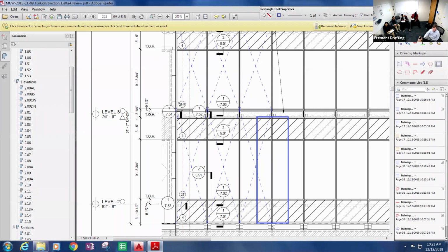So as I look right here, I've got 9.5 inches down here, so 3'10" minus 9.5 is 3'1", so 3'1" from the top of the floor. So let's say the anchor was 3 inches down from that, I'm at 2'10". So that's 34 inches. So it'd be 2 times 34, 68, divided by 175. So 68, it's almost a third. So I'm allowed about 3/8 of an inch, 5/16 of deflection, let's call it, for the cantilever portion itself.